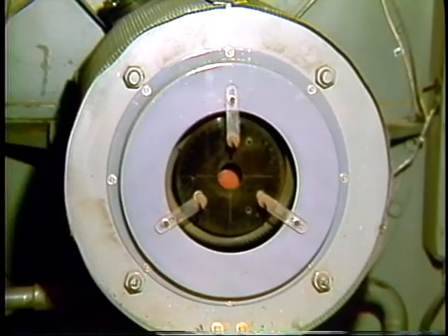Of course, for a short overnight shutdown of the machine, where generator maintenance is not required, the generator remains charged with hydrogen with the seal oil system in operation. To prevent excessive leakage from the seals, it is important that the shaft rotate continuously on the unit turning gear. It is quite apparent that operation of the hydrogen cooling system is much more complicated than generator cooling by air. You must become thoroughly familiar with the operating procedures for your particular installation.